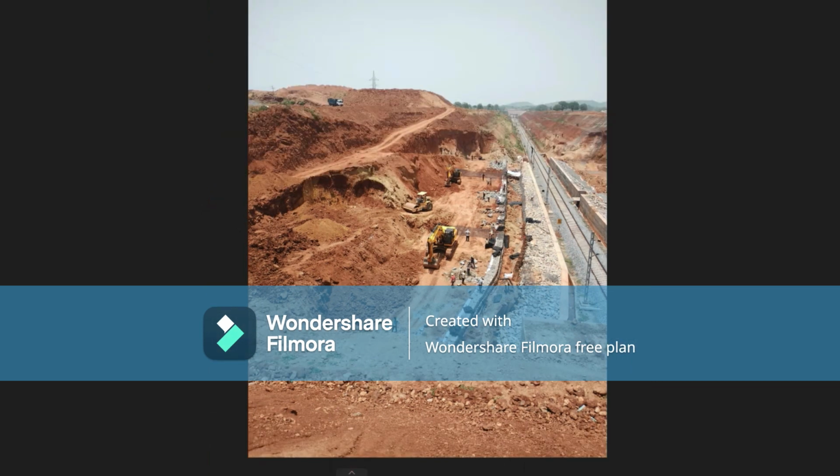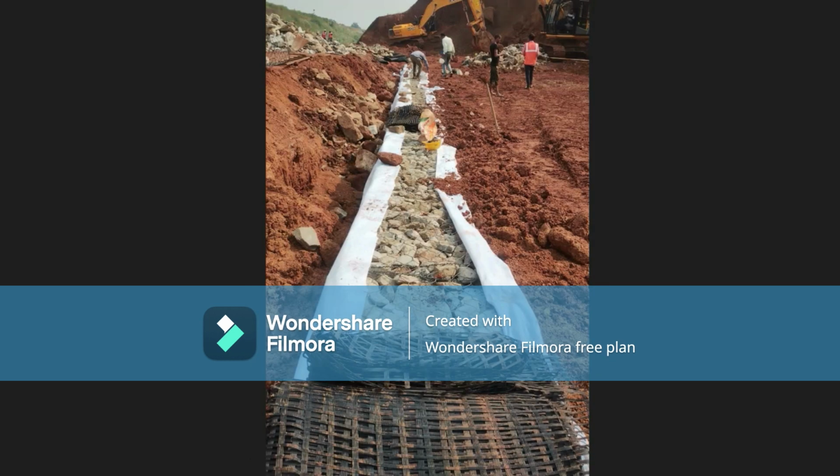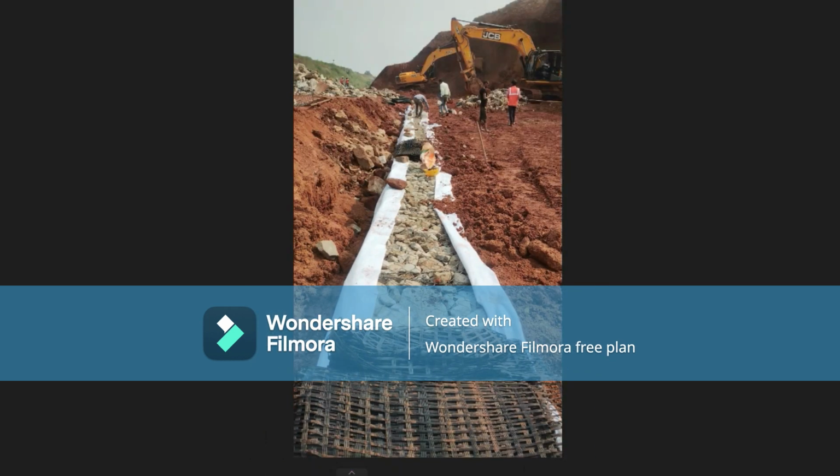Here we can see. After preparing the ballast, the railway track is done, and they also assemble the signal, telecommunication and electricity, and then the Gabion wall was started as the retaining wall. They first removed the loose material and started the Gabion wall, continuing their construction at the existing ground level, with the railway track level below the existing ground level.